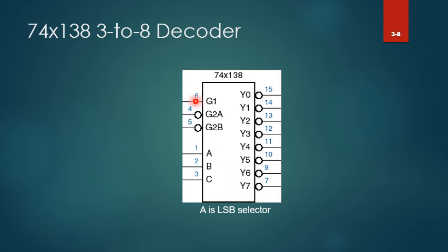Okay, so this is fixed by the designer of the chip 74138. But when you design it using Verilog code, it's up to you how many enable pins you want to design for your 3-to-8 decoder. For the chip 74138, there's a reason why they need so many enable ports: they are useful when you want to use multiple units of 74138 chips to build a bigger decoder.